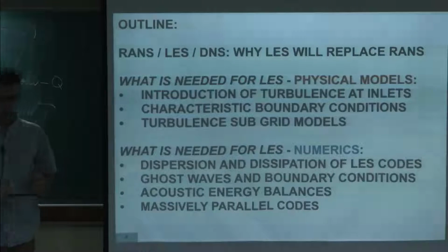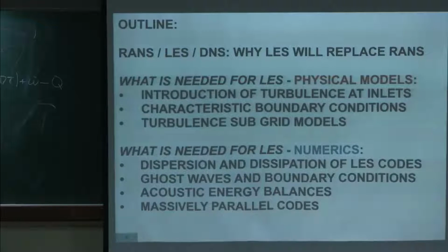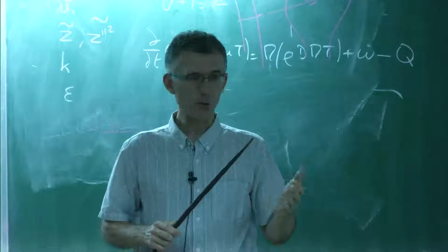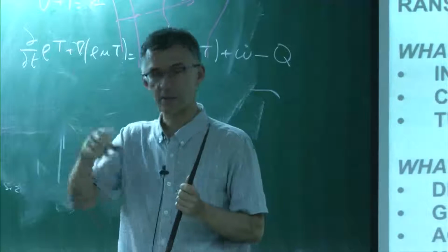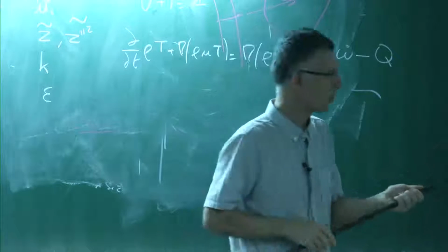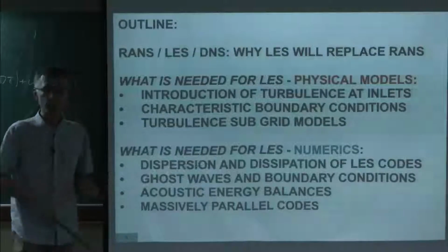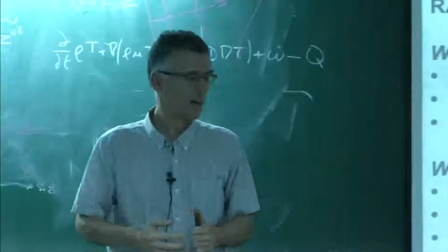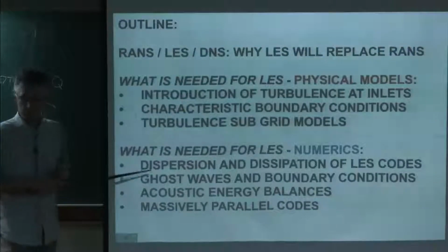But in CFD of combustion, usually when you do a steady computation, it's as if nothing is moving. You just look at a steady flow field. As soon as you go to LES, you recognize that you're going to have eddies and waves. And the first question is, if you create an eddy in the flow, are you propagating it at the right speed? That looks like, of course, you say, of course, yes. Well, no. The point is that in most codes, if you're not careful, the speed at which you're propagating a vortex can be wrong by 50%. It's moving, but it's not moving at the right speed. So if you do an LES with a code which has errors like this dispersion and dissipation, then it's not going to be a good code. So you need basically to change that.